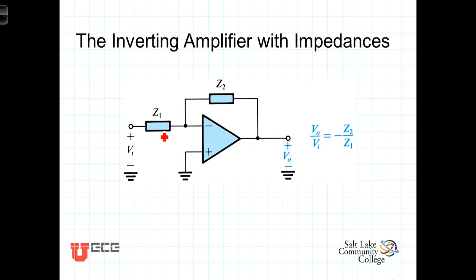In other words, we have I equals C dV/dt, and we also have V equals 1 over C times the integral of I(t) dt plus V_C(0), the initial value of the voltage. We can also look at it from the frequency perspective, and the frequency-dependent nature of Z_C now